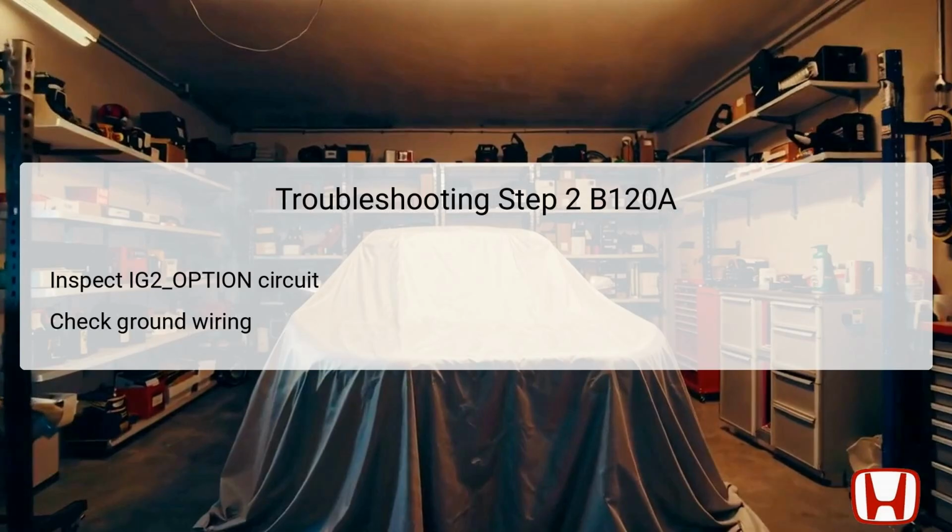The next step involves performing a detailed inspection of the IG2 option circuit, along with inspecting the ground wiring associated with the climate control system. The IG2 option circuit serves as a power supply and must show a normal state of 12 volts when the ignition is on.